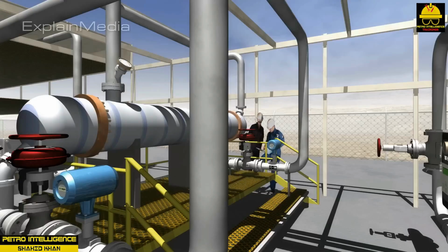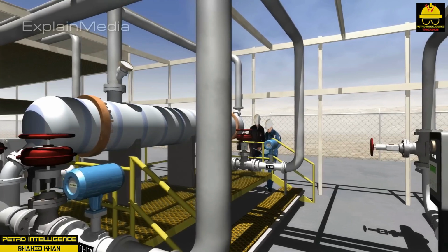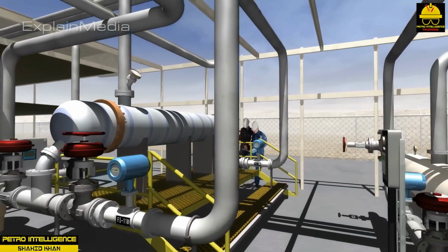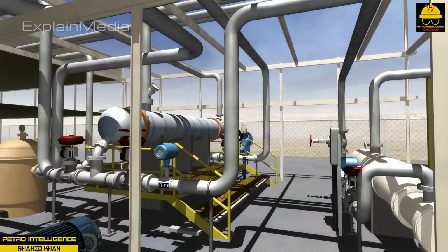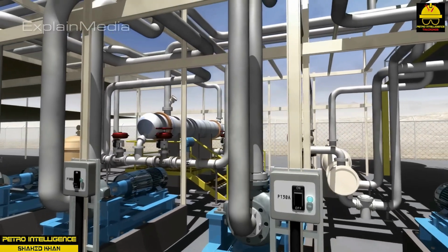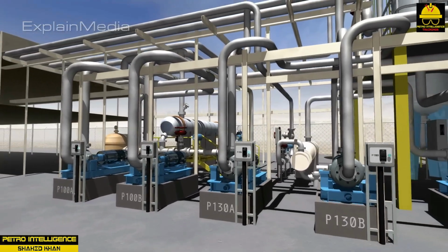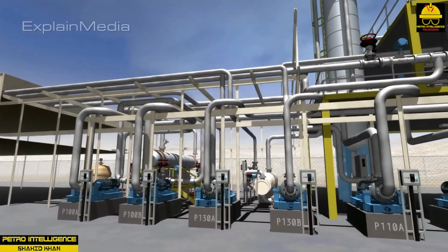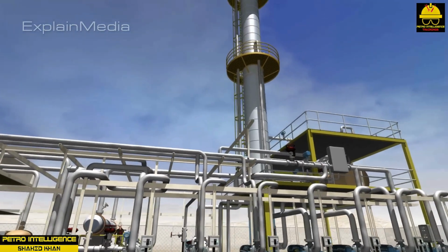Distillation separates the basic components or fractions of a mixture by their individual boiling points. During the distillation process, a mixture is heated until it vaporizes, then is recondensed on the trays or at various stages of the column, where it is drawn off and collected in a variety of overhead, side stream, and bottom receivers. The condensed liquid is referred to as the distillate. The liquid that does not vaporize in a column is called the residue. A distillation tower can be compared to a series of stills placed one on top of the other.